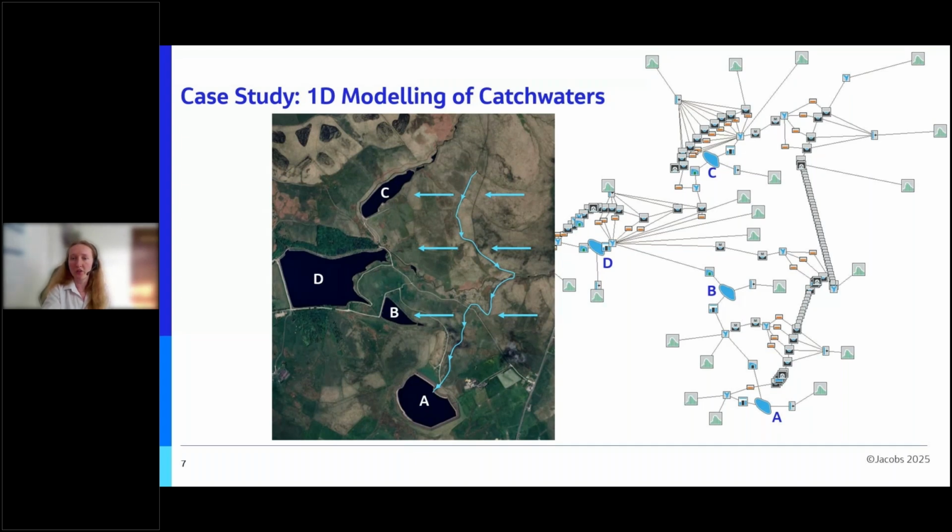The catchwater open channel was represented in this case with cross-sections and interpolates with lateral spill units on the right bank. The laterals are then connected to Muskingum units to represent the movement of spillages to each reservoir. Muskingum units determine the flood peak attenuation and the lag time of a flood wave as it passes through a routing reach. The catchments are all very small, and so the timing of the spillages would make quite a difference to peak flows within each reservoir. Therefore, modelling the travel time of the spillages was important, which is what Muskingum units are good for.